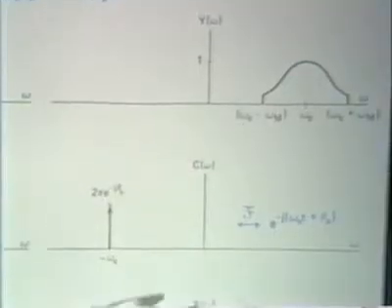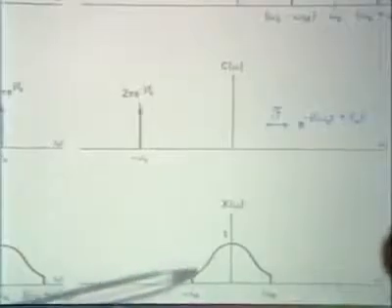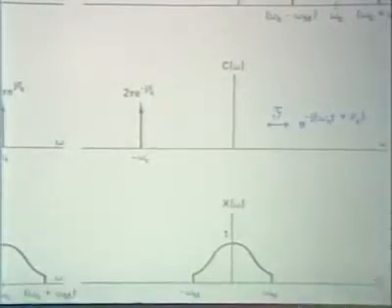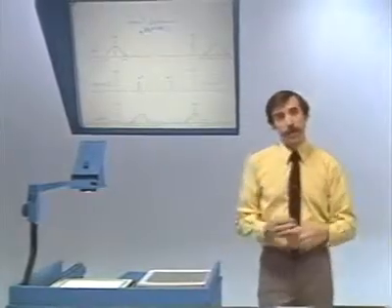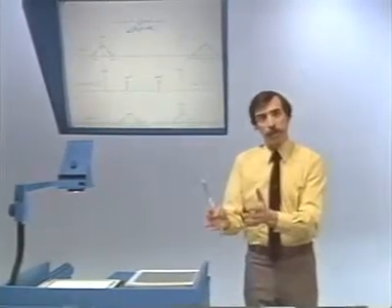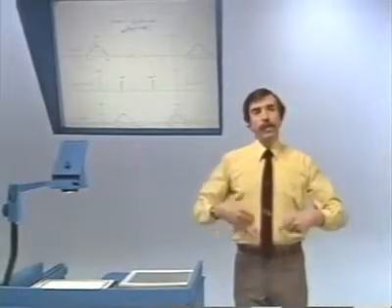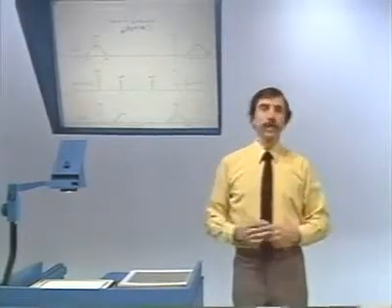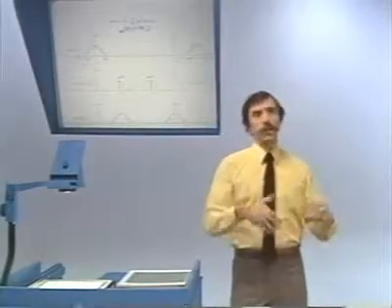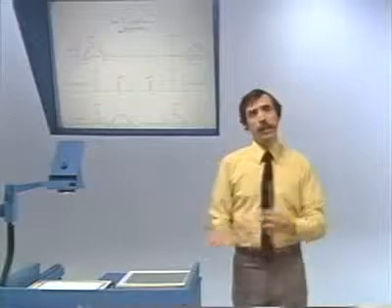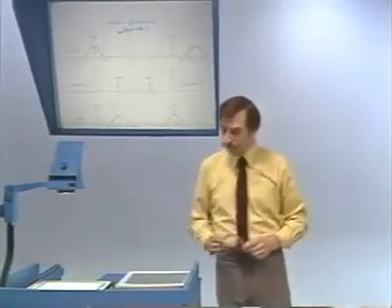So convolving these two together, the spectrum that we end up with is that. So we can track this through in the frequency domain. In the frequency domain, it says shift the spectrum up. When you want to demodulate, shift the spectrum back down. And alternatively, we can look at it algebraically in the time domain. And what it says is if you multiply by e to the plus j omega c t, then when you want to get back, multiply by e to the minus j omega c t.